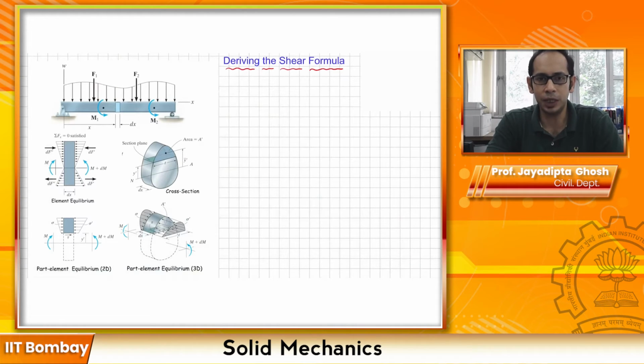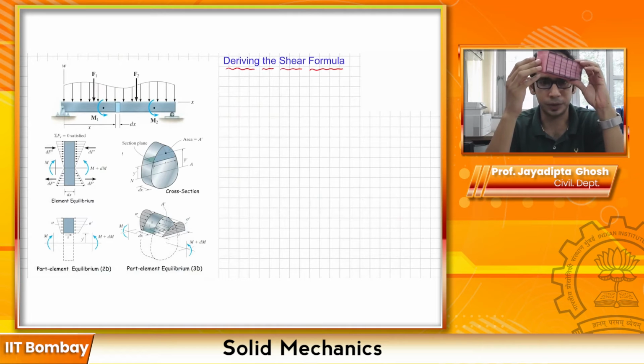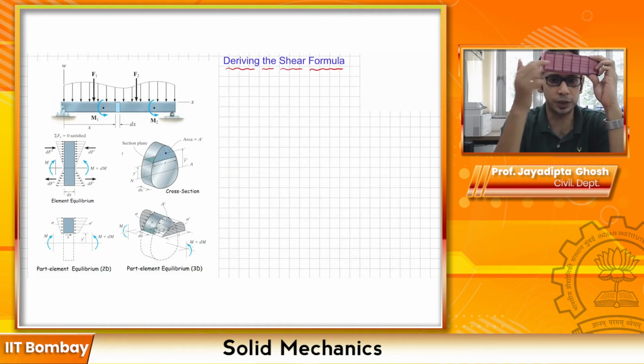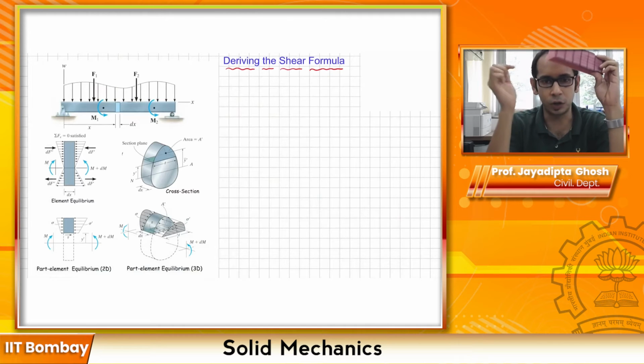Now we have already seen one very important thing. If you take a beam and you are computing the stresses at any particular cross section in the beam, the shear stresses arise on the interface, that is fine because your applied load is acting at the interface, but at the same time this transverse shear stress also gives rise to a longitudinal shear stress at every single point. If you traverse across this section, at every single point, whatever is the tau going down, you have a complementary shear stress which is acting along the longitudinal axis.